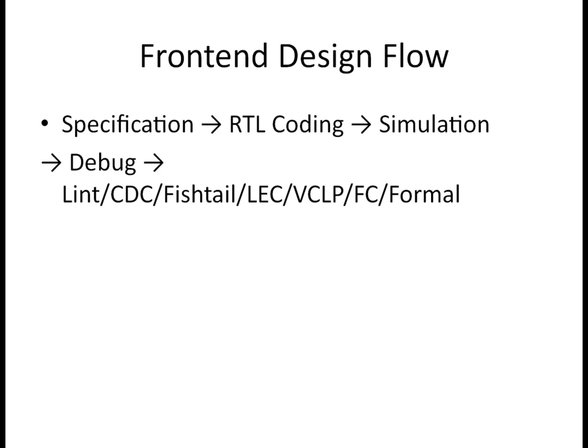Okay, and in that case, normally the expectation is data has to travel from one domain to another in one clock cycle. So that is why these are called exceptions. We are giving exceptions to a few paths. Okay. So again, if the tool is not able to apply multi-cycle path for some reason, we need to debug those, and accordingly we need to talk to the designer and fix this. Okay, this is brief about the Fishtail.